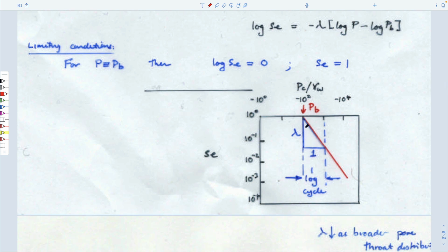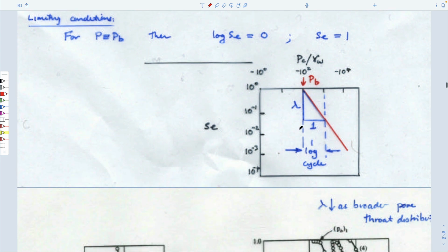And if we do that, then it actually plots in exactly this form. And that allows us to be able to say the things about this curve. It might not seem immediately obvious why we want to do that, but we can define this behavior in terms of this point here. So in terms of log saturations, the effective saturation here is equal to 10 to the 0. So this is equal to 1. At 1, we still don't have the bubble of air penetrating it, so this by definition has to be the bubbling pressure.